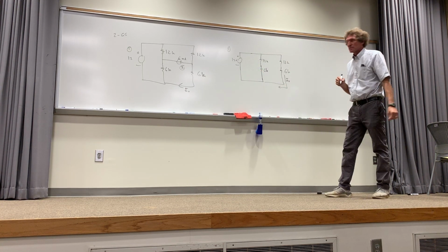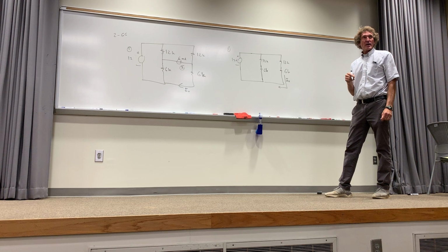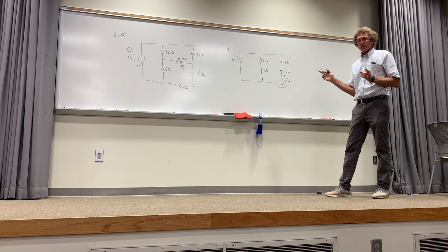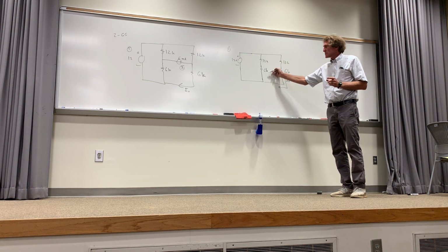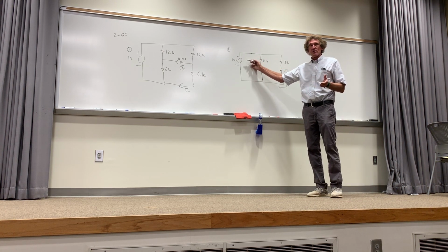Y'all agree with me here, class? Who asked this again? All right, you see what I'm doing, right? Yes, sir. By this time, most of you pick up on this fairly quickly. These two are in series, do you agree? That's a total of 18 K ohms. These two are in series, that's 18 K ohms, right? They're both across 12 volts.